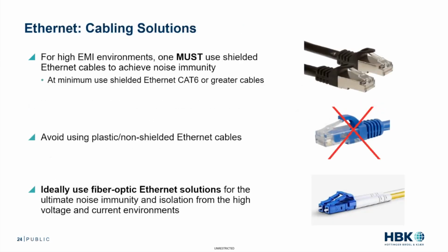And I hear every once in a while a customer calling up saying they start their electric drive test, and all of a sudden the communication to their power analyzer is lost. And the first thing I mention is, well, do you have or are you using shielded Ethernet cables? And that's usually the case for the issue. You get high EMI environments, especially from the pulse width modulated signals coming out of the inverter, and you need to make sure that you're using shielded Ethernet cables to achieve noise immunity.